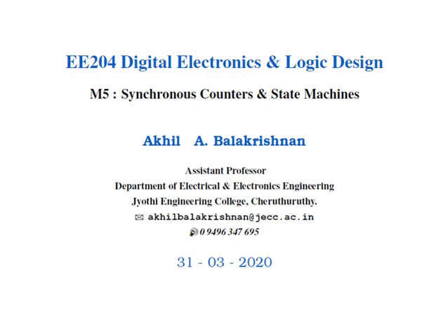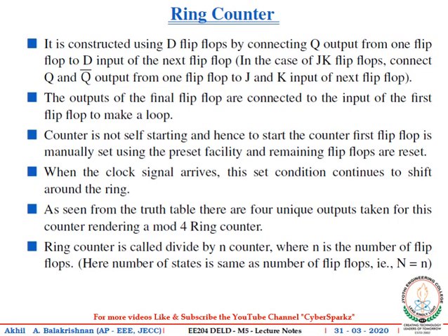Counters and State Machines. Today we are going to study a special type of counter called a ring counter. A ring counter is a synchronous counter having a lesser number of valid states. For example, if we are taking 3 flip-flops in the design, the counter can have a maximum of 8 valid states. So with 3 flip-flops, a ring counter circuit will have fewer than 8 states. To be precise, the exact value is 3 itself.